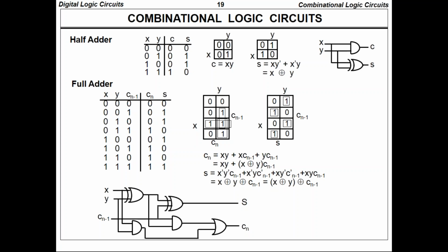What is a combinational circuit? A combination of logic gates, like AND, OR, like half adder and full adder. Sequential circuits also have the normal logic gates. Then what is the difference between combinational and sequential? Sequential circuits have a clock and flip-flops.